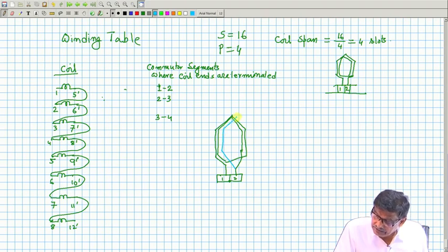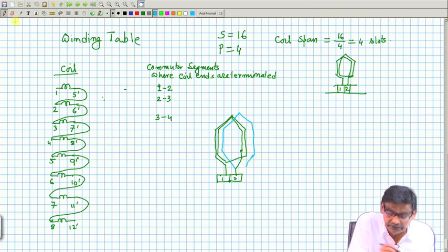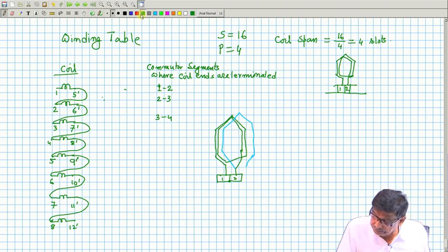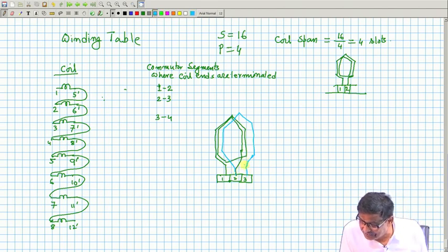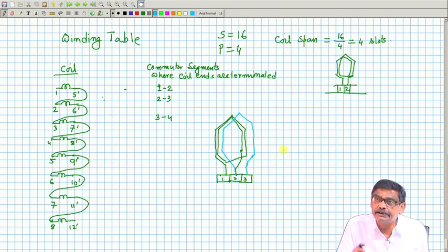So, next coil, first thing is commutator segment 2, this blue one, and its return will be terminated in commutator segment 3. So, from the junctions, those vertical lines are coming to the commutator segments, and these commutator segments, because they are connected to the shaft, will also rotate.